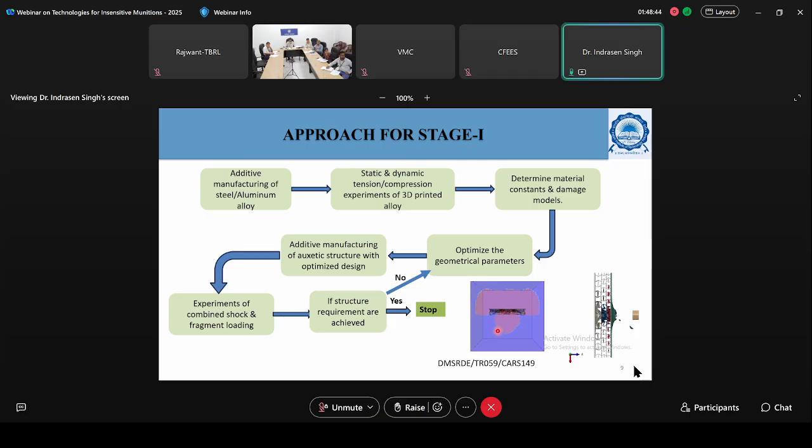But in this work, we could not benchmark our simulation due to lack of experimental facilities. Number two, here we have used many layers, and we have used Kevlar also. In Abaqus, the damage model available for Kevlar doesn't have strain rate sensitivity, and it's suitable only for unidirectional fibers. So now we have developed a code for an implemented model for Kevlar, which can capture strain rate sensitivity also, and which can be used for woven type of Kevlar. This work we have done, but due to lack of experimental facility, we could not benchmark our results.